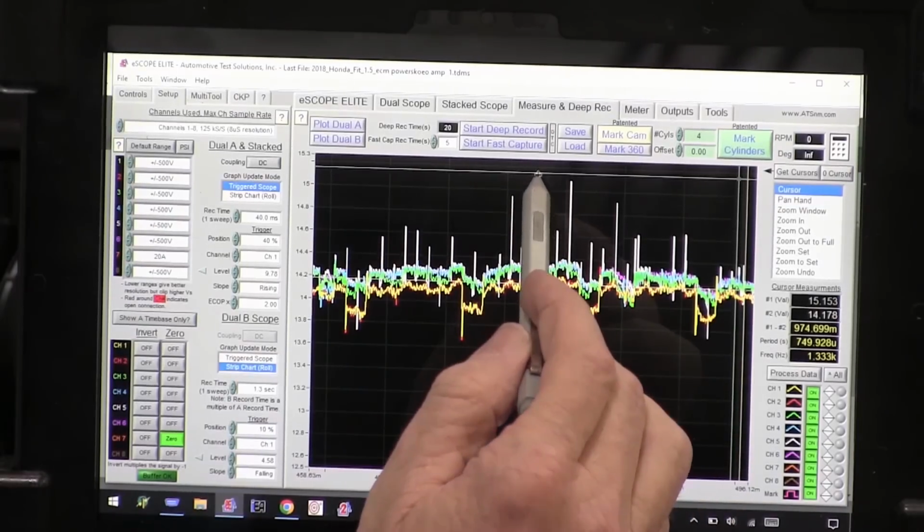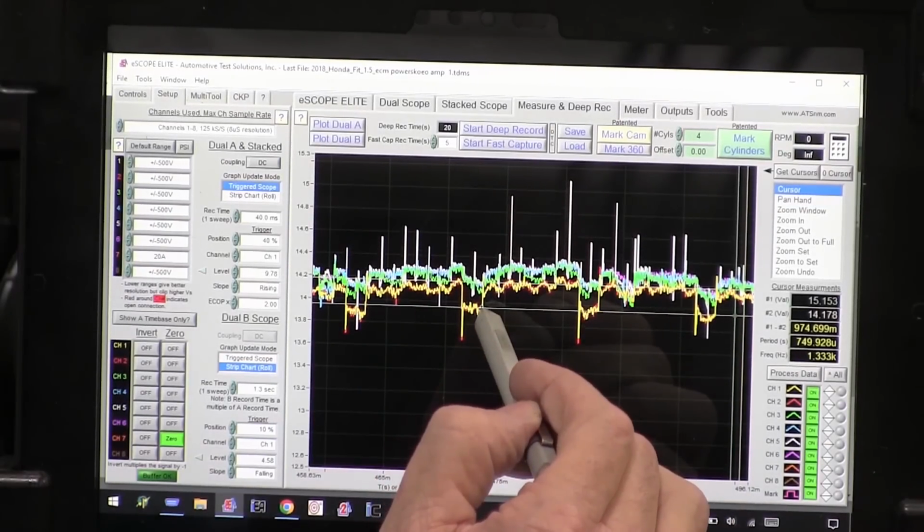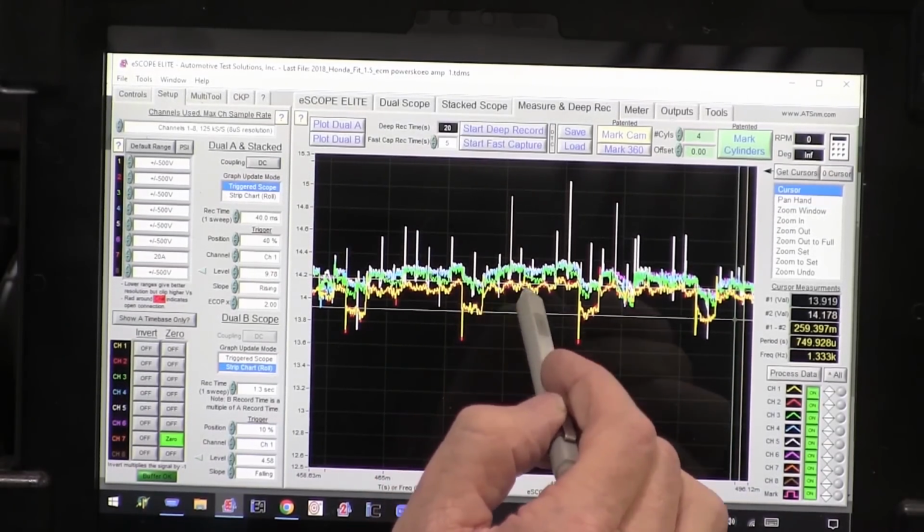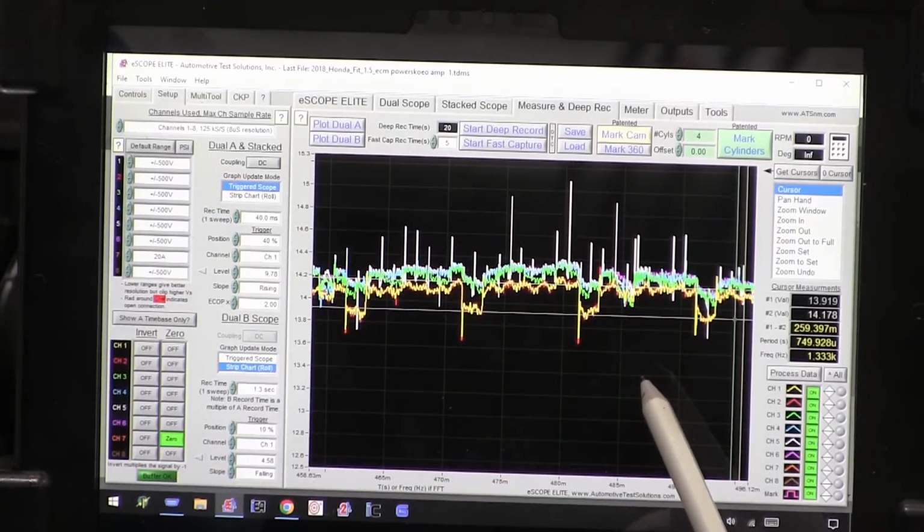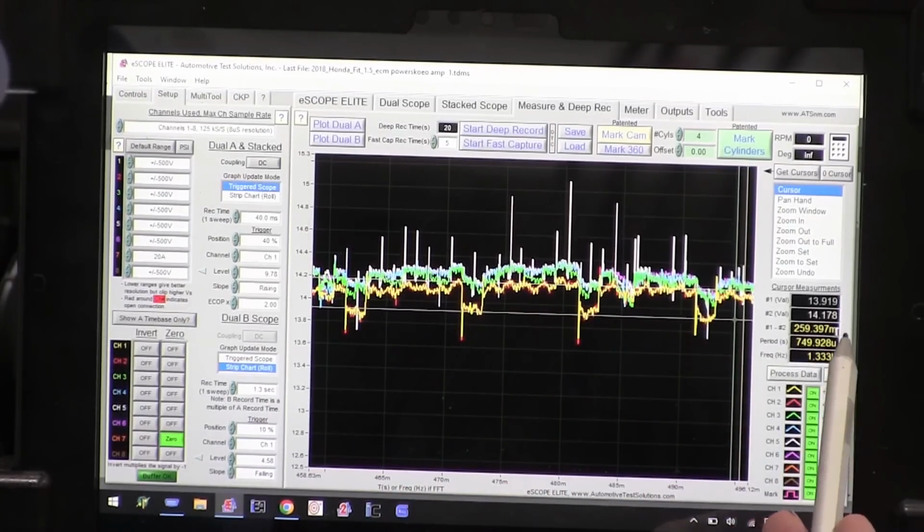Right through the yellow there, and to the bottom of the yellow, that looks like my biggest drop. Again, 259 millivolts. Now at a quarter of a volt on the power, from all of my experience, I've chased a lot of problems like this and never could find that's a problem. I'm not chasing this, it's not enough.